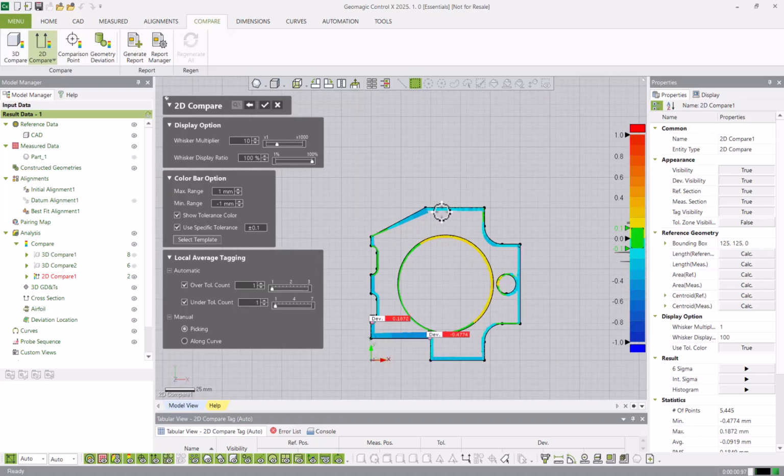And you can click across the points of interest to find the deviation between the CAD and the scan. So I can click in this green zone, and I would be able to make my deviations there. I can click in this particular point, and the software would show the deviations between the section of the CAD and the section of the scan across the plane that you had selected.